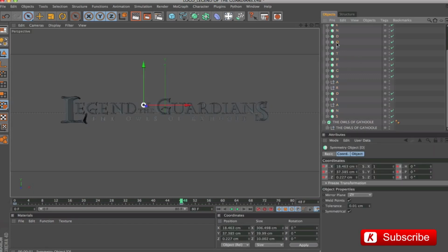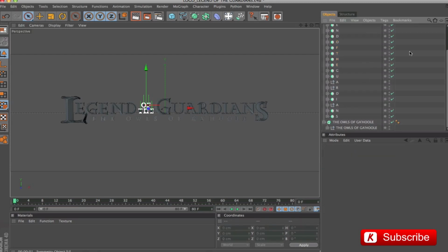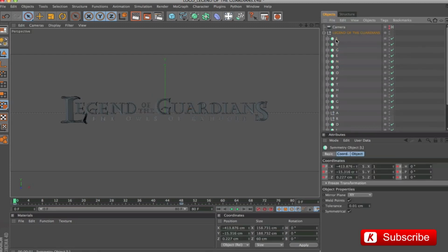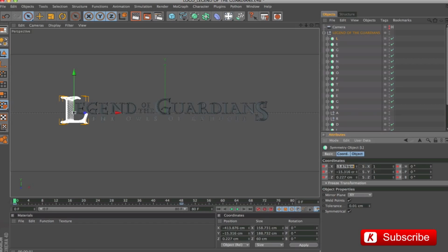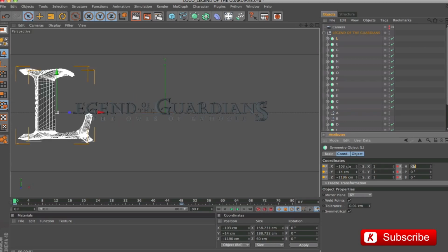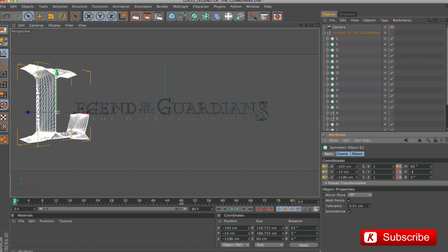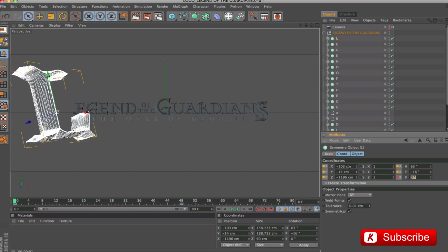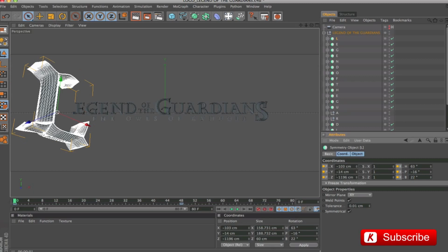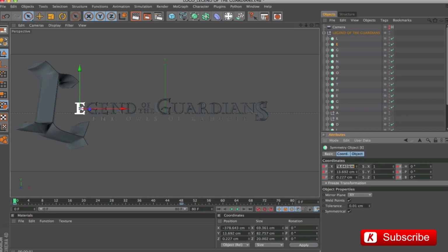We select the letters that make up a B and modify the timeline position from 48 frame to 44. We select the L letter and insert the following coordinates: X, minus 103, Y, minus 14, Z, minus 1196, rotation 63, minus 16, 22. Follow the scheme on the video for setting the parameters of the letters' animation coordinates.